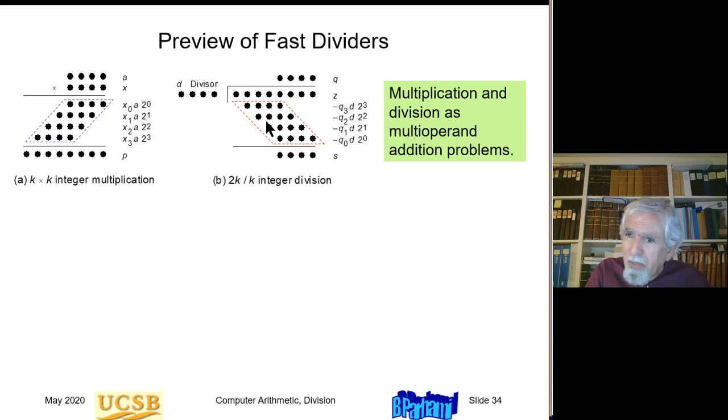Okay, here we can do the high radix one that we did there. Basically try to determine maybe 2 bits of Q in one cycle. So I need 2 cycles in that case for this 8-bit by 4-bit division. Okay. So high radix dividers is what we will study.